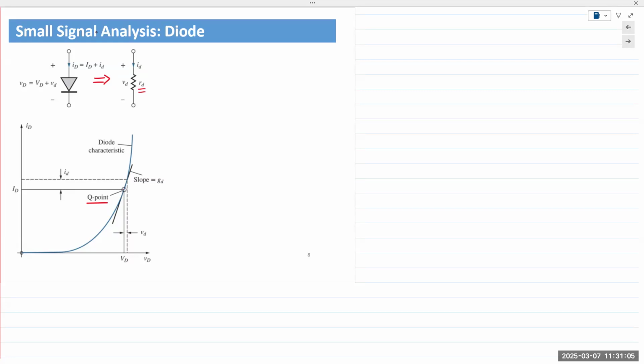It doesn't have to be 2 points on either side, but typically, that's what I like to do. But any point that's shifting away from the Q point will give you a small value of the change in the voltage and a change in the current. So this is the original Q point right there. And this is the shift away from the Q point.